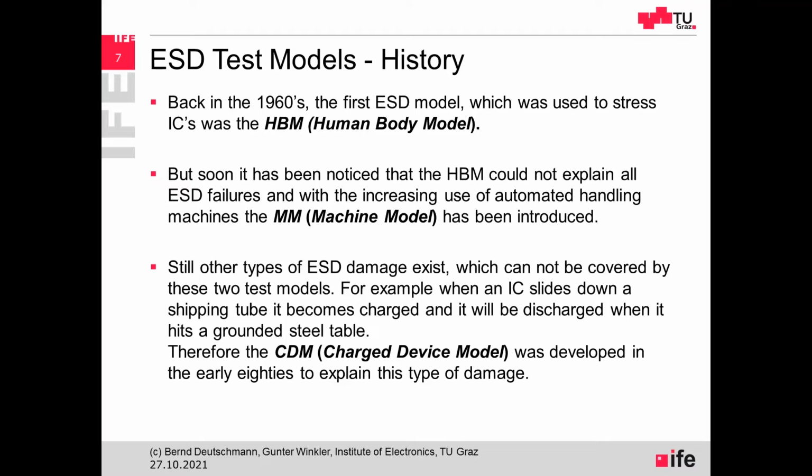And then in the 1960s, the first ESD model was generated, the so-called HBM model. HBM in this case stands for Human Body Model, which is simulating the electrostatic discharge that can happen when a charged human person is touching an integrated circuit, and thereby discharging into the microelectronic structures of these integrated circuits. So this was also the time frame where the first ESD protection structures were integrated.